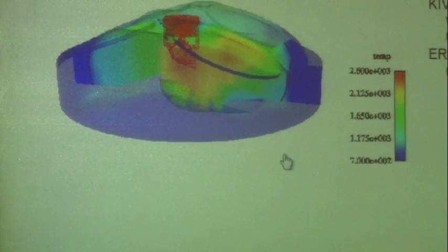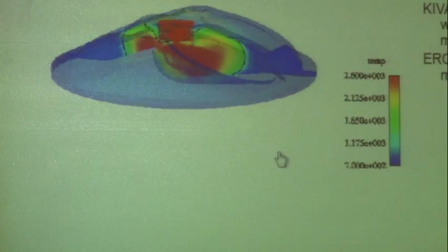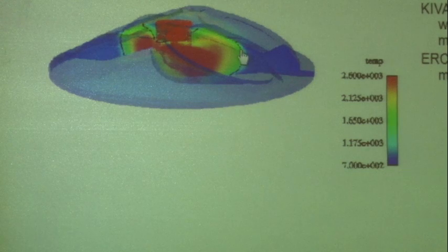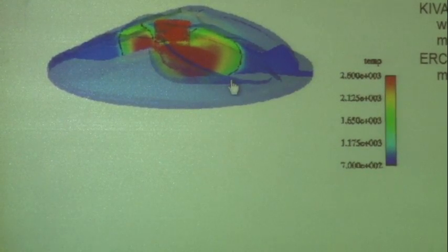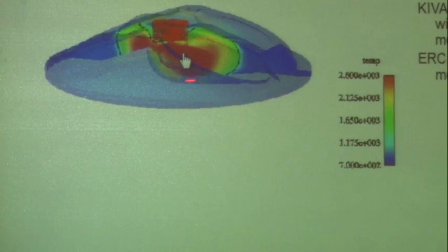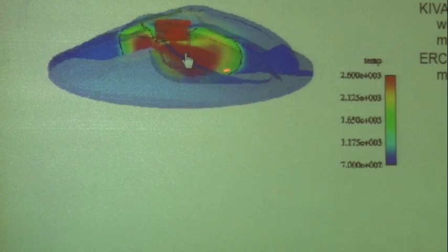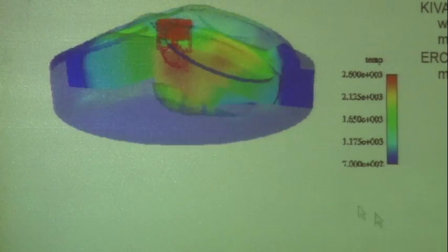And the color contours here are temperatures. Let's just show that one more time, the spray, ignition. So this black line that you see in the plots here is the G equals 0 surface. And behind that you have high temperature gases being compressed also by the propagating flame. And the flame is propagating out into this pent roof combustion chamber geometry.